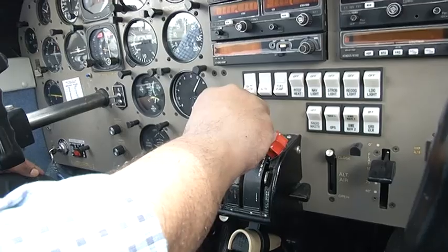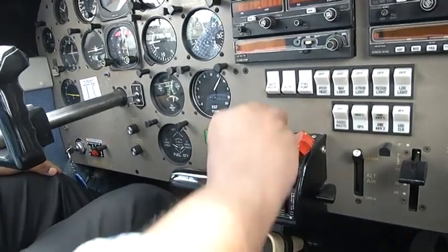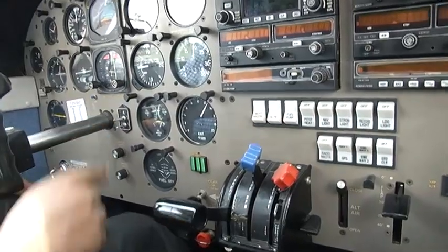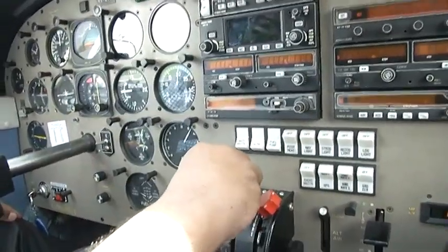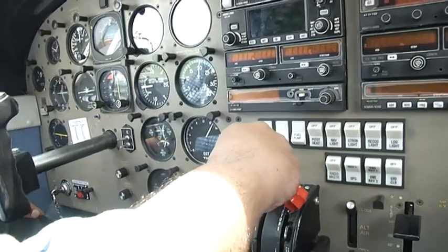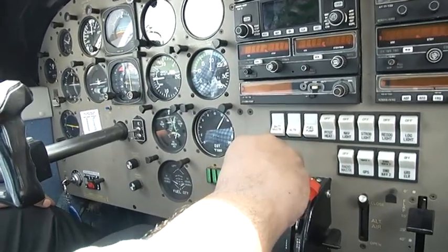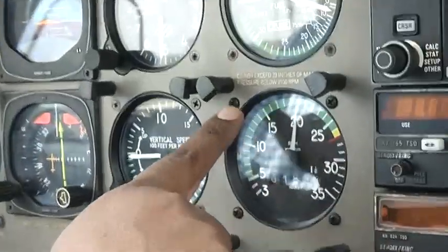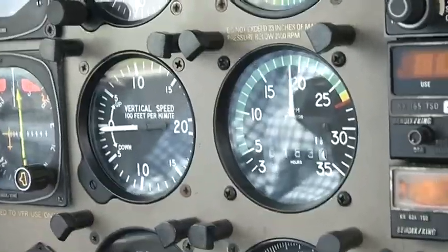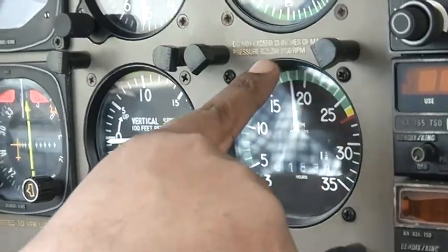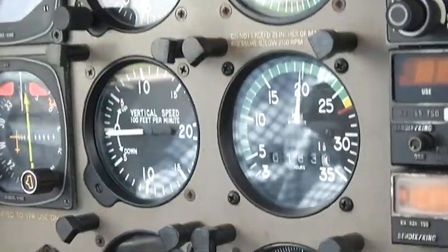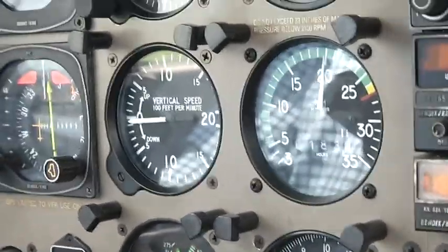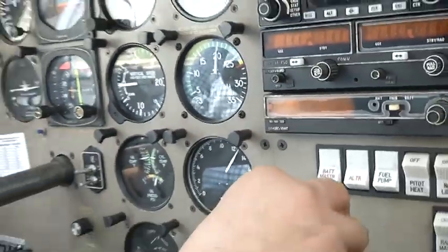Just see it again. I'll show it once more. Just observe the drop in RPM. This is 2000 at the moment. It should be less than 500. Just observe that it was something around 300, 350. So this was all about the propeller check.